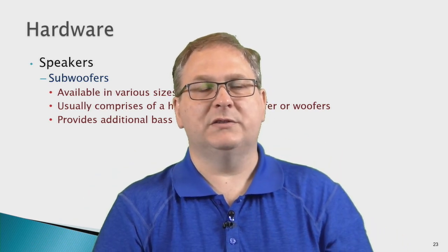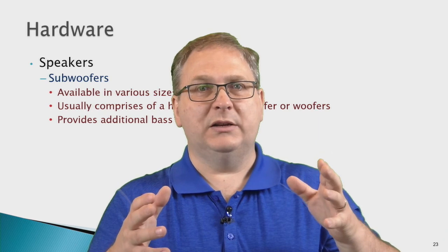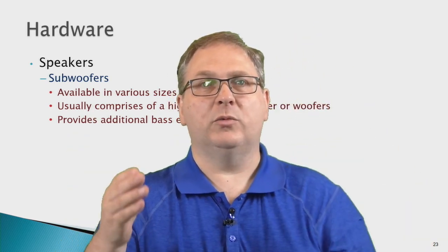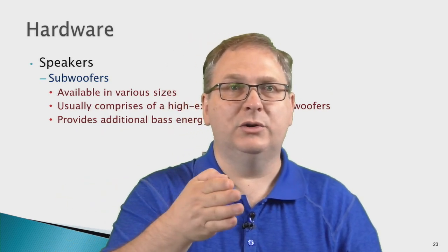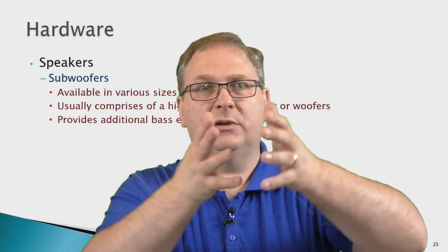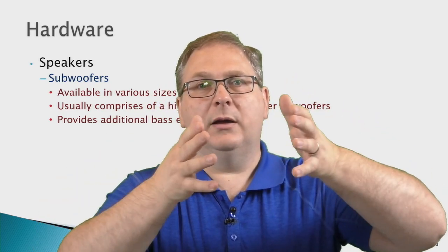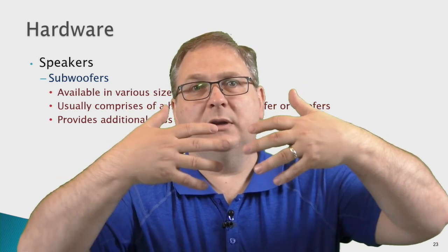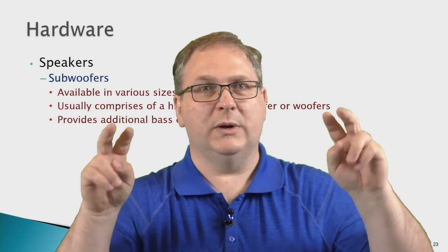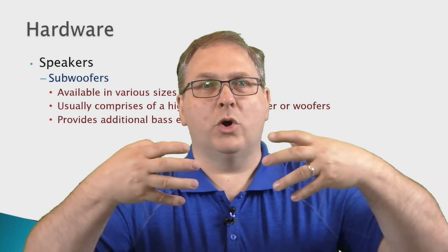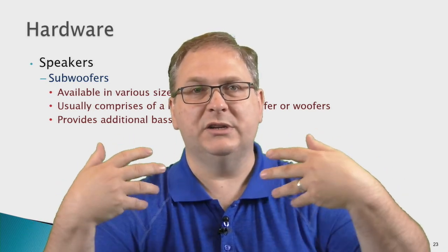What happens is that on a woofer inside of a normal speaker, when you're asking it to go beyond what it was intended to do, it actually warps as it's moving, and it causes what's sometimes referred to as cone distortion, where the cone starts to change shape, and therefore you start to hear differences in sound.